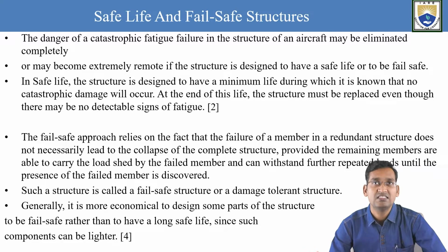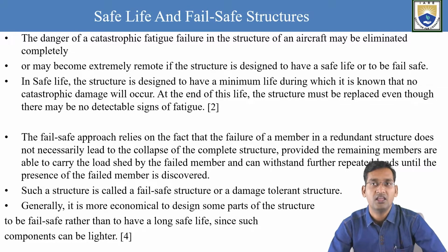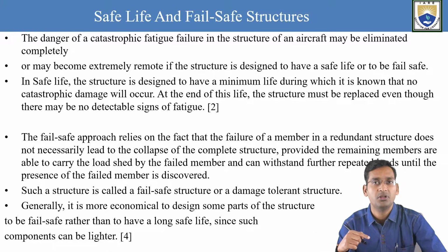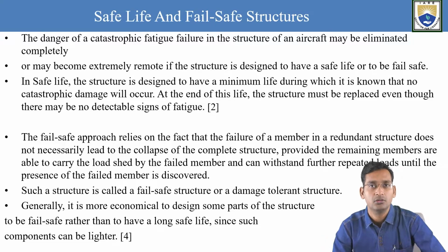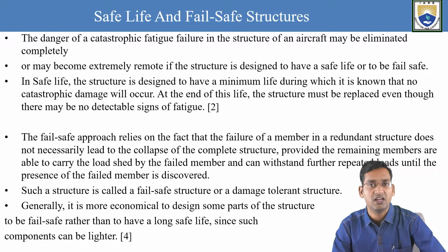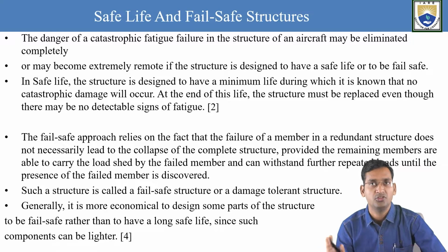So now what is safe life? Safe life is when the structure is designed to have a minimum life. Remember, the minimum life during which it is known that no catastrophic damage will occur. Suppose you purchased this pen and you have an exam, and you have only a half-filled pen. What will you do? You will change the pen. Why? Just for safety, so that in the exam it won't run out and you can use the new pen. That comes under safe life. It's not that some small amount of refill is left inside and you go by that refill to write the exam. You will change to a new pen. That is safe life.